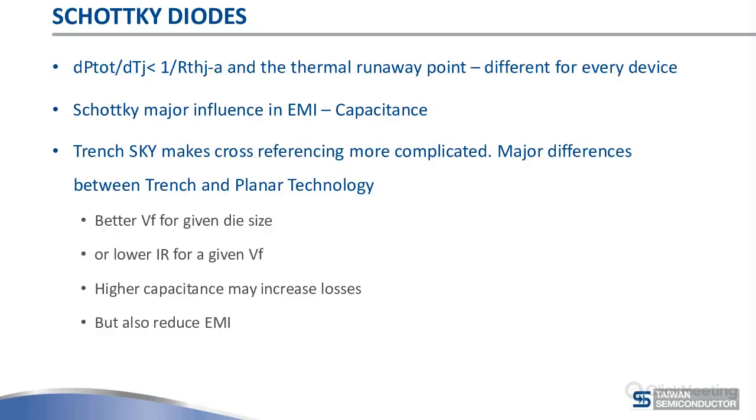The first formula here is the formula for the thermal runaway point. This is different for every Schottky device. Also note that it is dependent on the thermal resistance. We are currently writing a white paper on the thermal runaway of Schottky diodes, the quality of Schottky diodes and junction temperature. This is a subject of another set of webinars in two or three months' time.